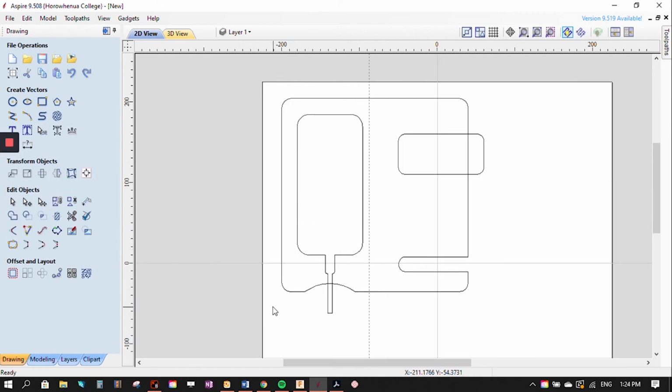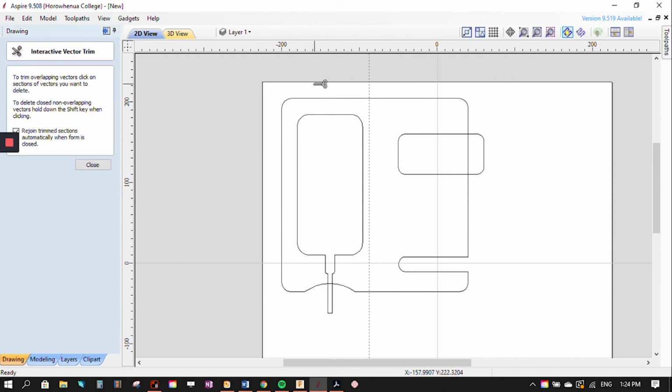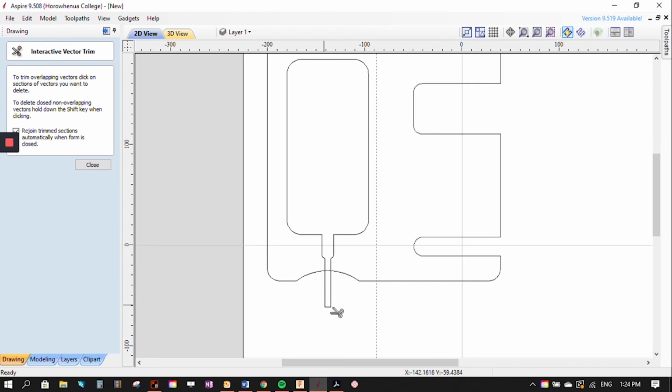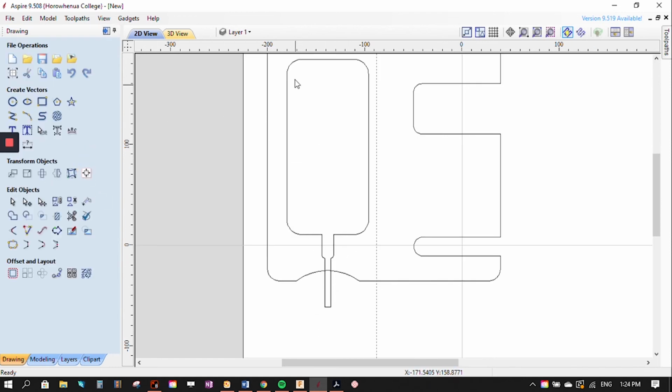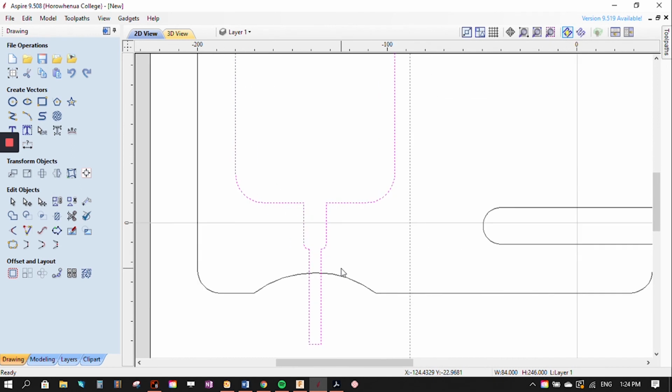Okay, so now another important thing for you to know, as you go about this final point of cutting things out. Before you cut out all of the edges of this pocket, you actually want that pocket, so this outside shape, to be extended down below. Because you're going to cut that out first, and you want the 6 millimeter mill tool, as it's coming down, to go down past there and cut that groove out. And then once that's all done, this path is going to come along afterwards and cut that little edge off, right?